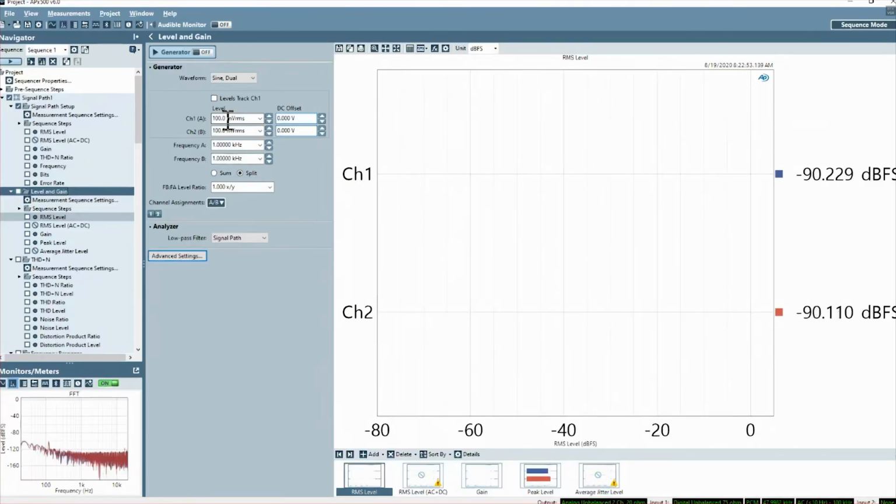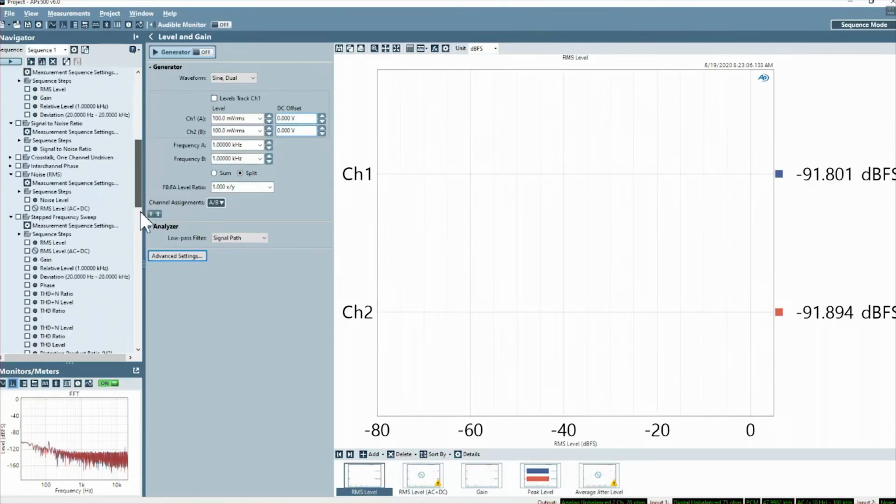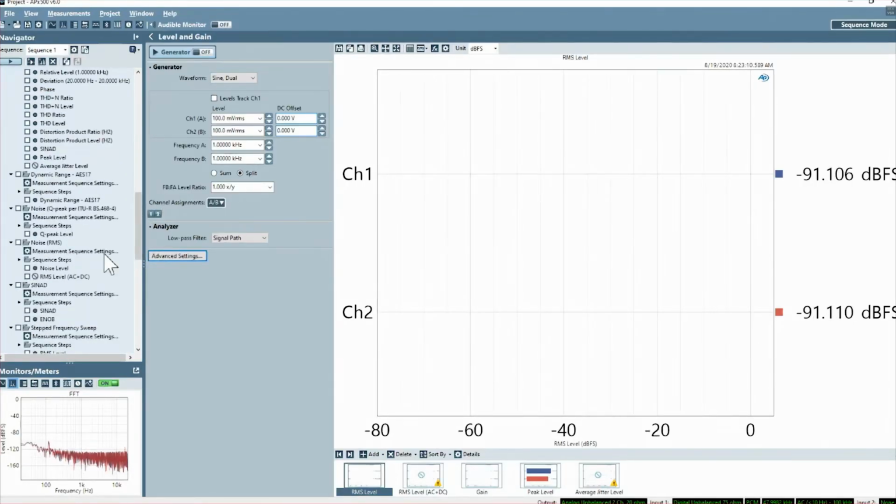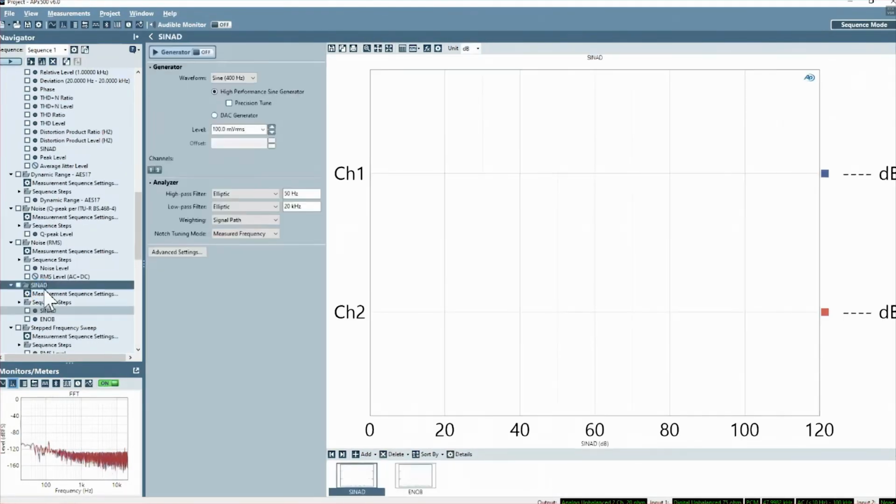Okay, thank you, Daniel. I have another question asking for a demonstration of SINAD measurement, SI90. Yep, sure, I kind of ran out of time, but let me take a look at that. For those who may not know, SINAD, I'm not actually sure what the correct pronunciation is, is the reciprocal of THD plus N. It really is 1 over THD plus N, and it's expressed in dB.